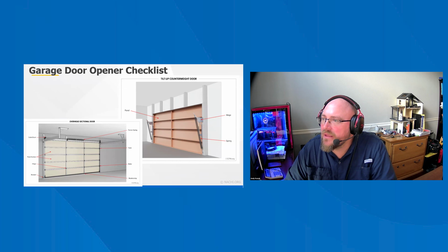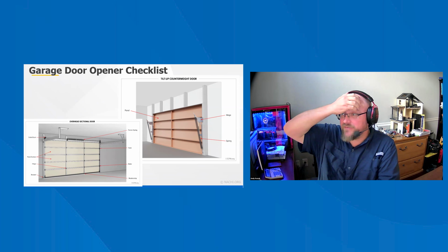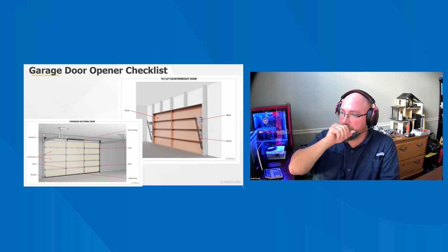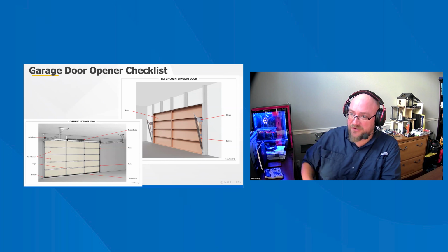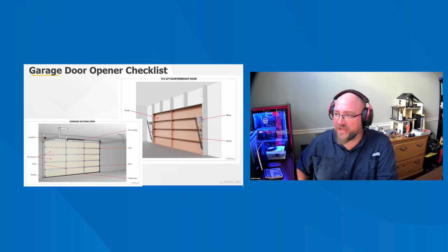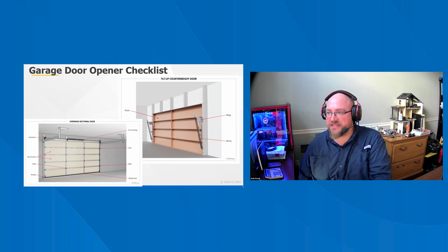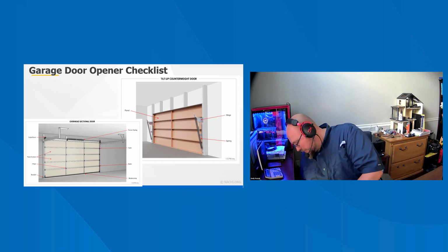If you observe a problematic situation with an overhead door, you should notify the homeowner and the occupants immediately and recommend they contact a trained garage door system technician. The garage door is typically the largest moving object in the house, and many of its components are under high tension. Improper installation or maintenance of a garage door can create hazardous conditions that can cause serious injury or even death.